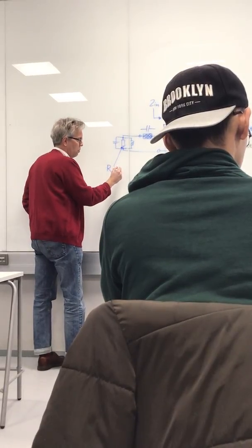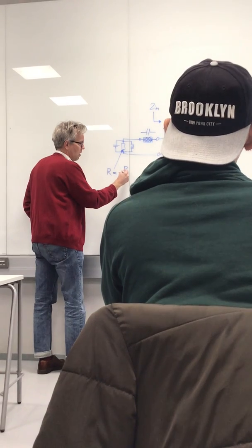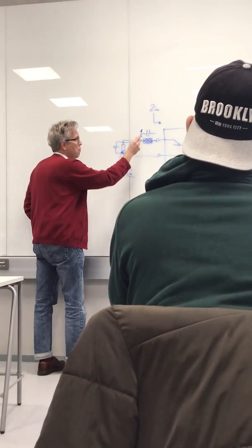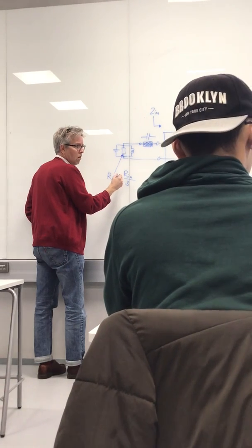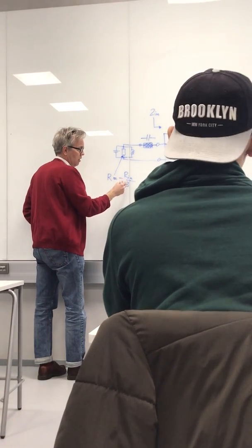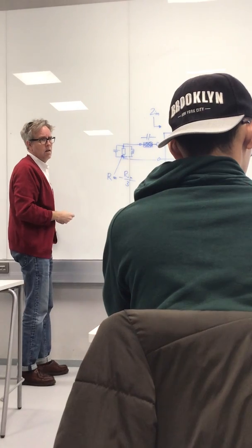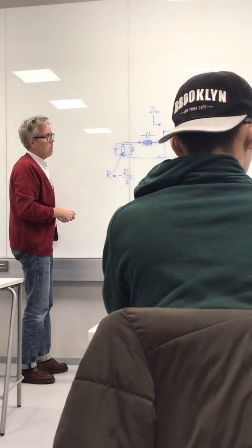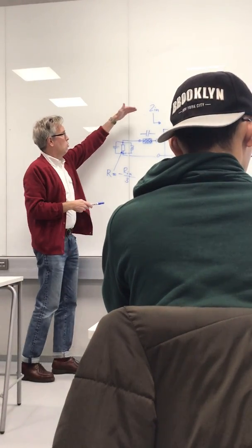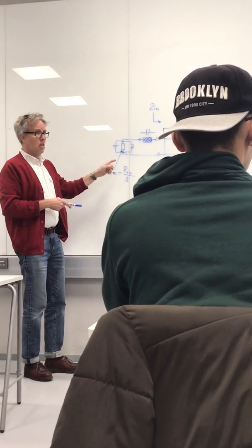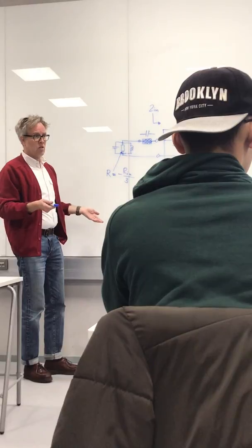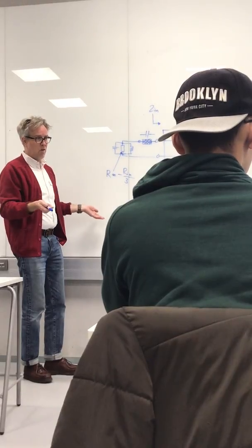This value should be the real part of the input impedance multiplied by minus and divided by 3. So for example, if in our case this was minus 30, minus times minus 30 is plus 30, divided by 3 equals 10.